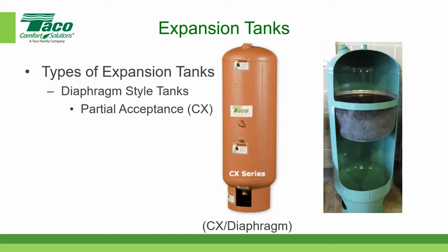Right. And do you have any symptoms of a failed diaphragm? Yeah, so based on what we had just talked about, this is supposed to be the air here, and then the water is down at the bottom. Let's assume that there's a hole here on the diaphragm. Over time, the air will go into solution into the water. The water will find its way through this hole and fill up the entire tank. And eventually, hopefully someone realizes it and it does not set off the relief valve. But if it fills up with water, we sometimes say it's waterlogged. So you can actually just depress the Schrader valve, and if water comes out of the Schrader valve, then you know that the diaphragm has failed. That's a very simple test.